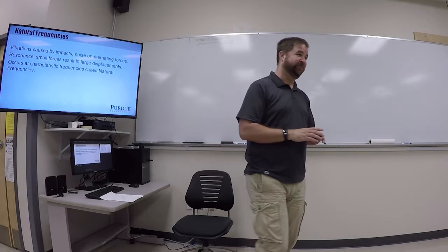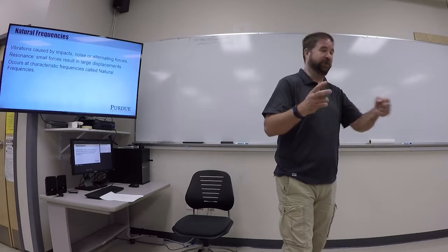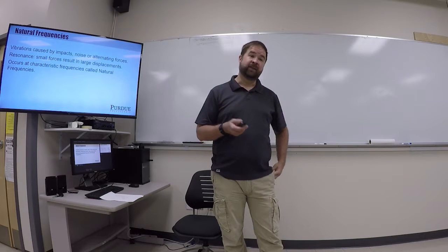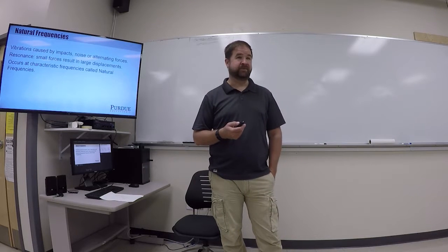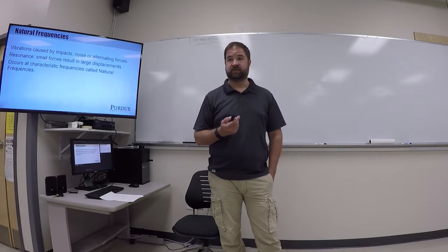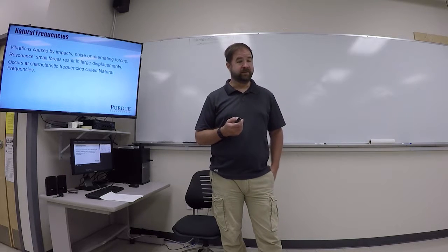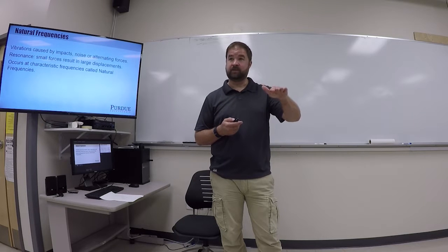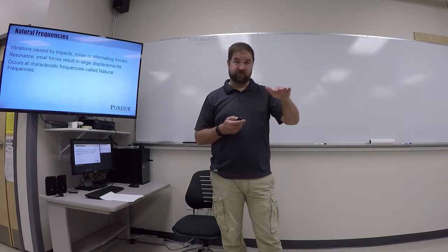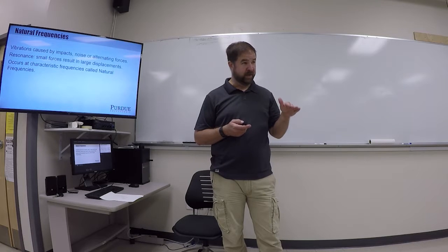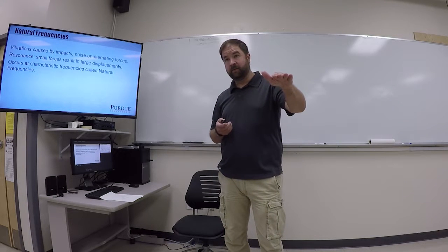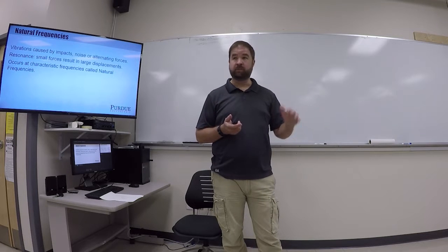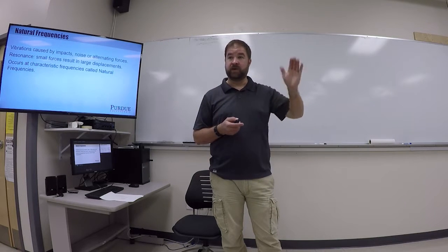Okay, so really bad situation. And of course, the poor person in the car is getting shook all over the place. Now, the thing that person obviously didn't realize, and I wasn't going to try to yell at them at 65 miles an hour, is they were driving at the natural frequency of that unbalanced tire. To stop it from vibrating so badly, if they slowed down or sped up, it would no longer be at its natural frequency, and it would still vibrate, but it wouldn't be the ridiculous bouncing off the ground kind of